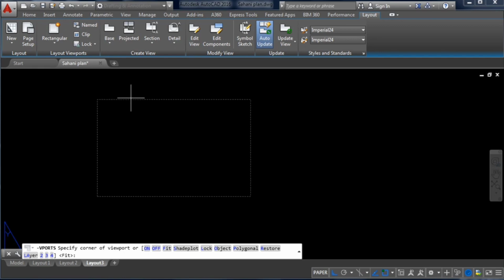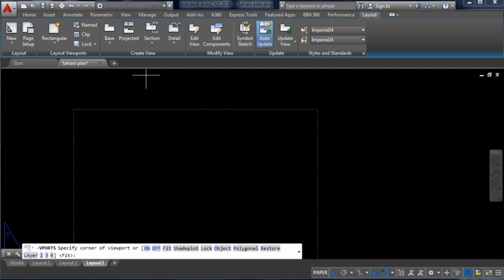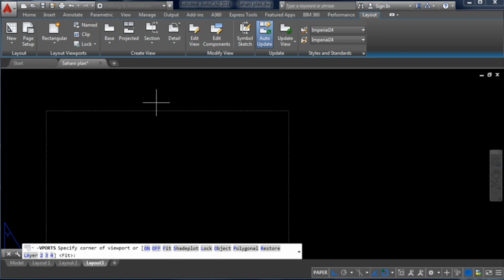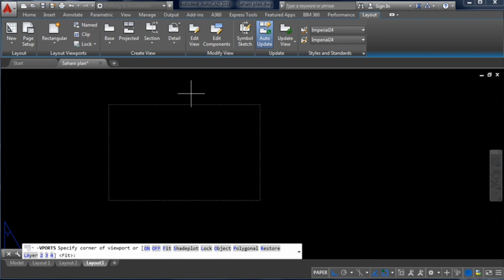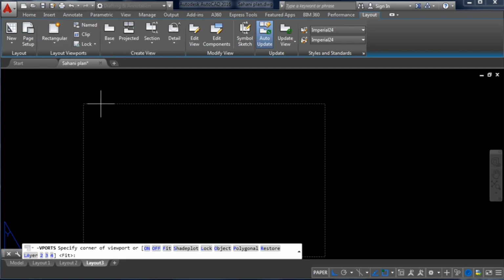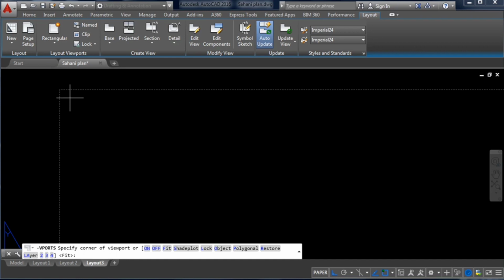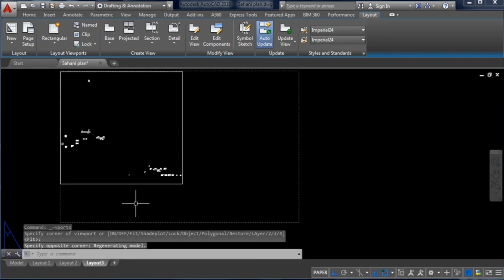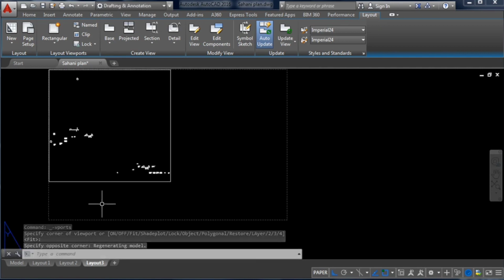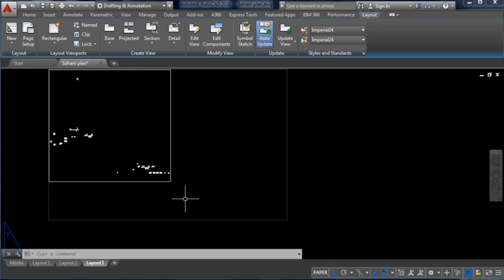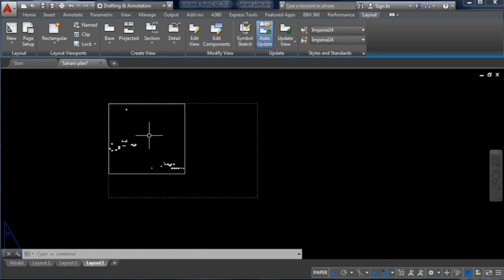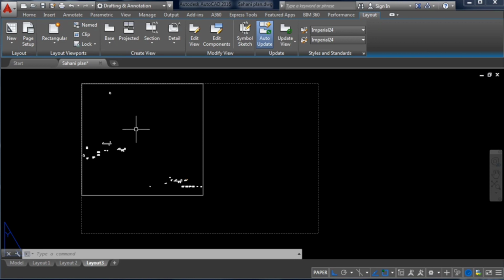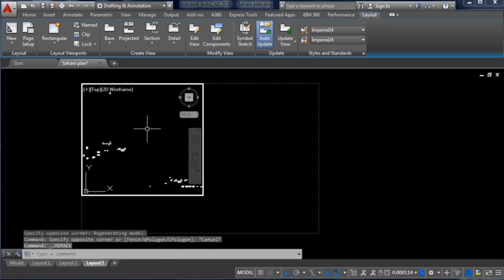Outside of this imaginary line, you cannot print. The printer will not support anything written outside of this line. So you have to put the viewport within this dotted or imaginary line. I am creating the viewport from this corner up to here, because at the bottom of this viewport you will have to write the consultancy name, stamp, your name, scaling, etc. I have taken a viewport, and to enter into this viewport you just double click within it.